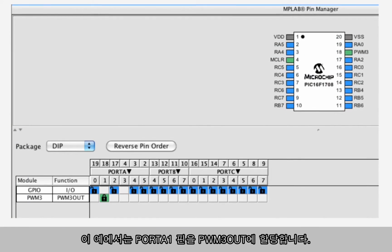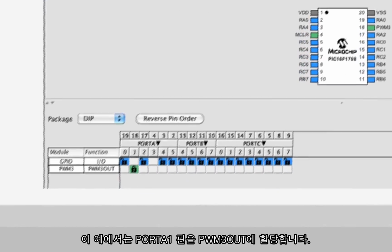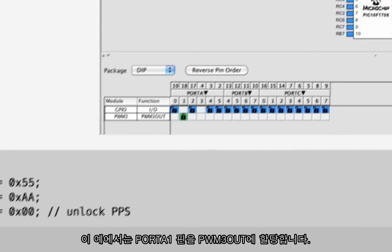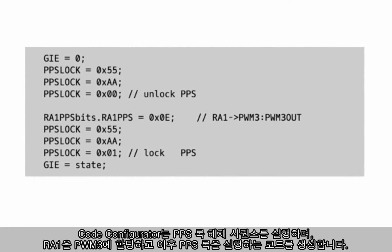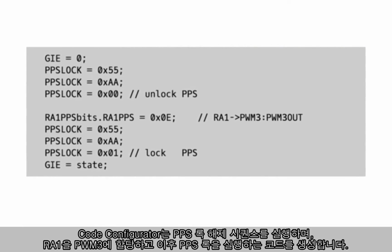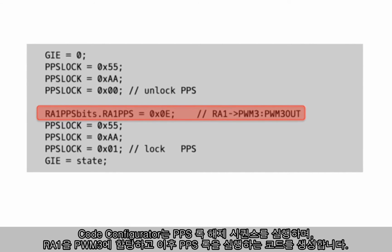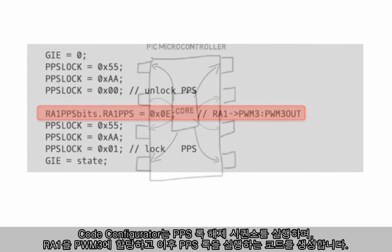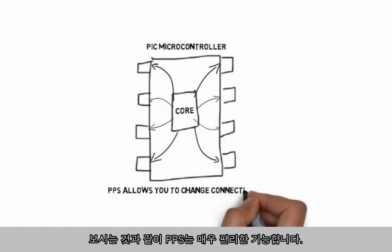Here's a very simple example showing the port A1 pin connected to the PWM3 output. The code configurator produces the unlock sequence, then the register setting for the RA1 to PWM3 connection, followed by the lock sequence. As you can see, the Peripheral Pin Select is a very useful feature.